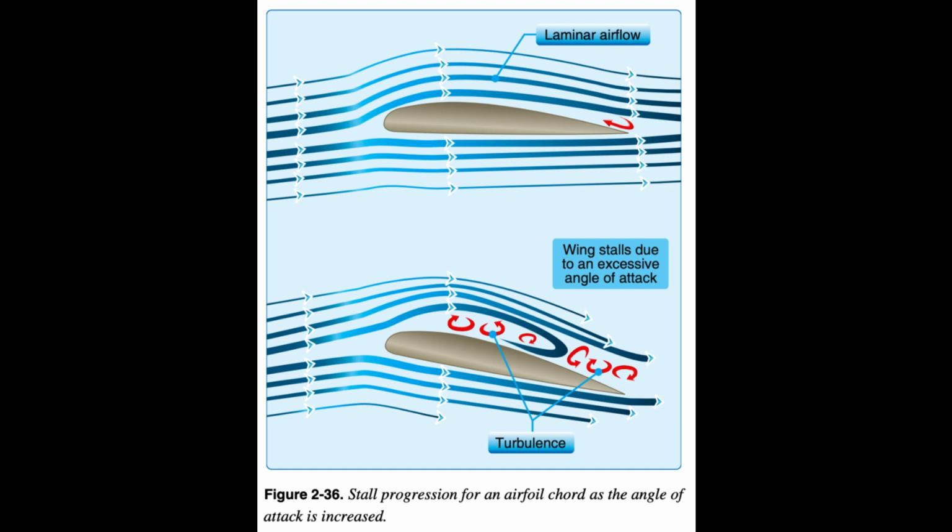Because the AOA of the WSC wing root chord/nose is so much higher than the AOA of the tips, the nose stalls before the tips. It is similar to stalling with the airplane canard, in which the nose stalls first, the main wing, or tips for the WSC aircraft, continues to fly, and the nose drops due to lack of lift. In most normal situations, the root chord/nose stalls first because it is at a much higher AOA. The tips continue to fly, making the WSC wing resistant to a complete wing stall.